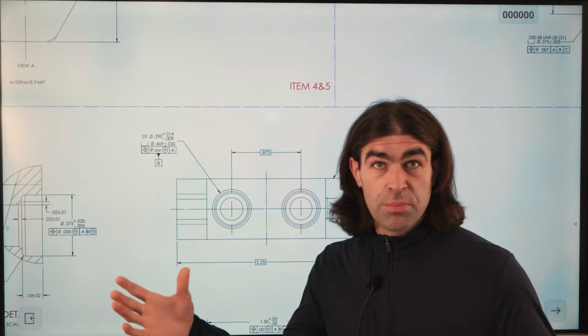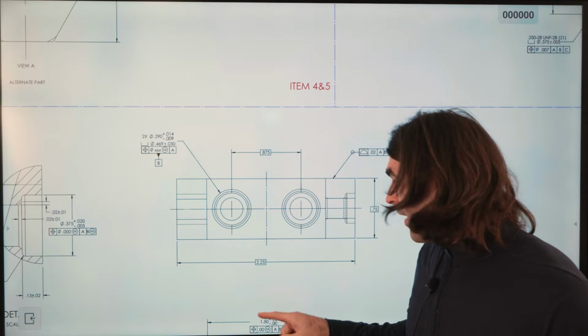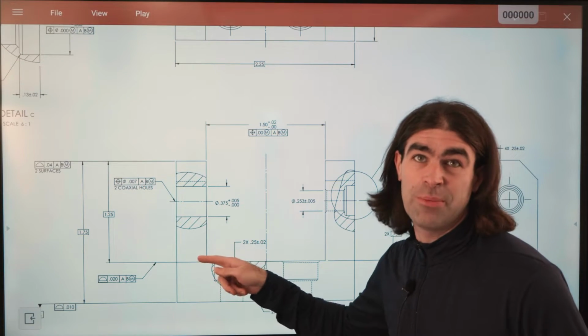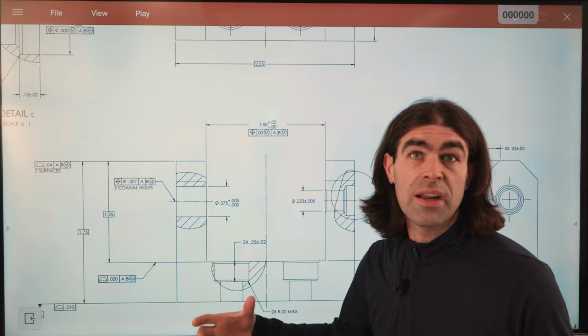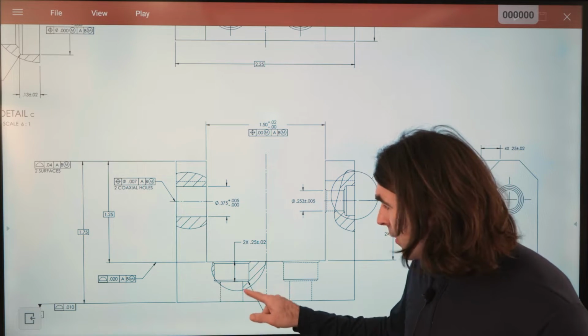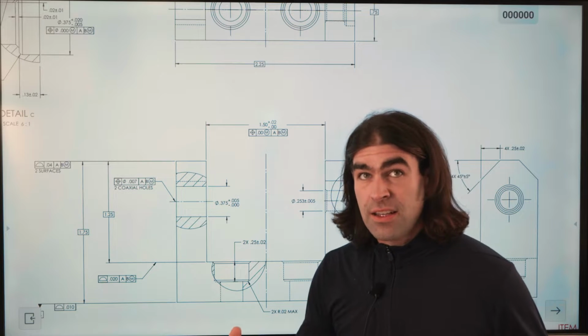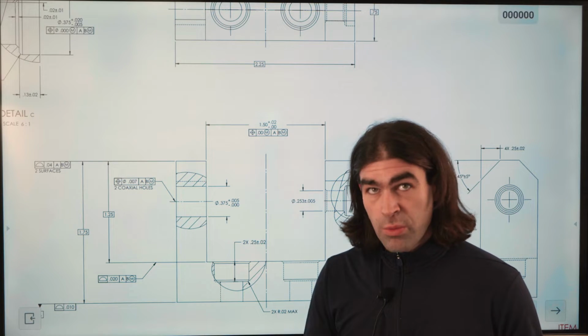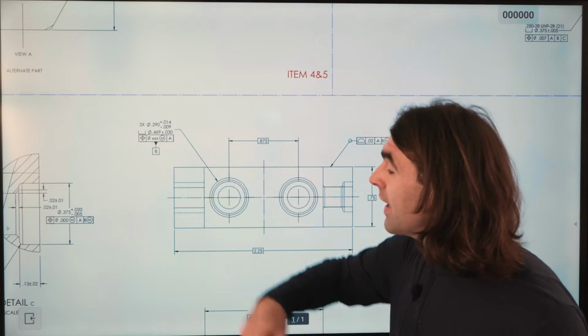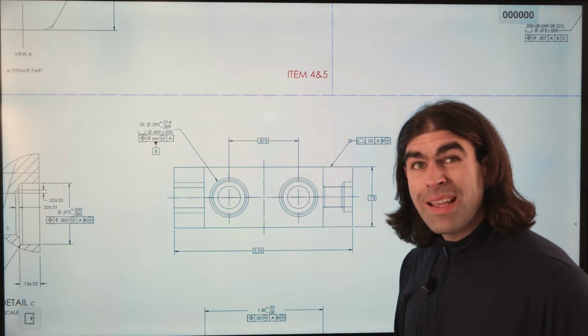The other one can be as big as it needs to be. In this case, the counter bore, there's no real size limitation on it. It could be huge, right? It's not doing anything other than providing clearance. The clearance hole, on the other hand, can't get too big because of the bearing area we just mentioned, right? So we're going to apply our position tolerance here, MMC.